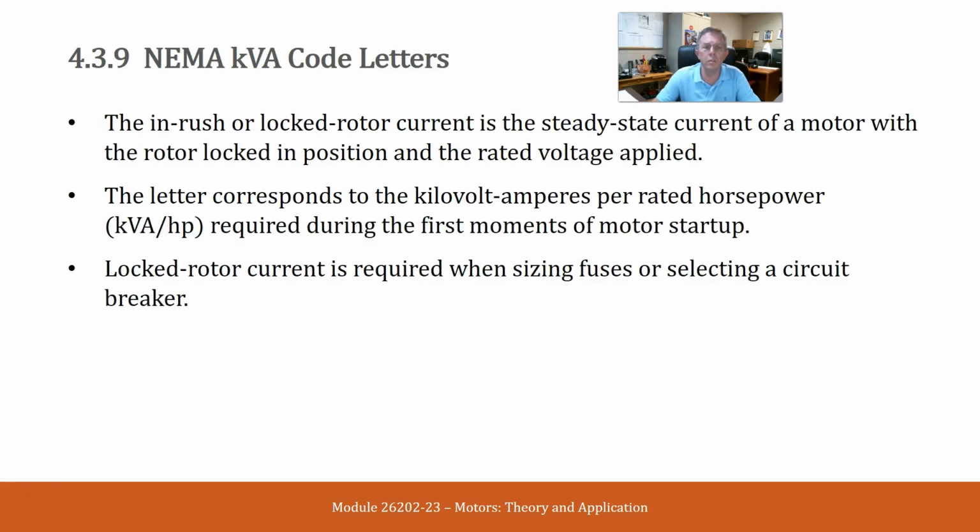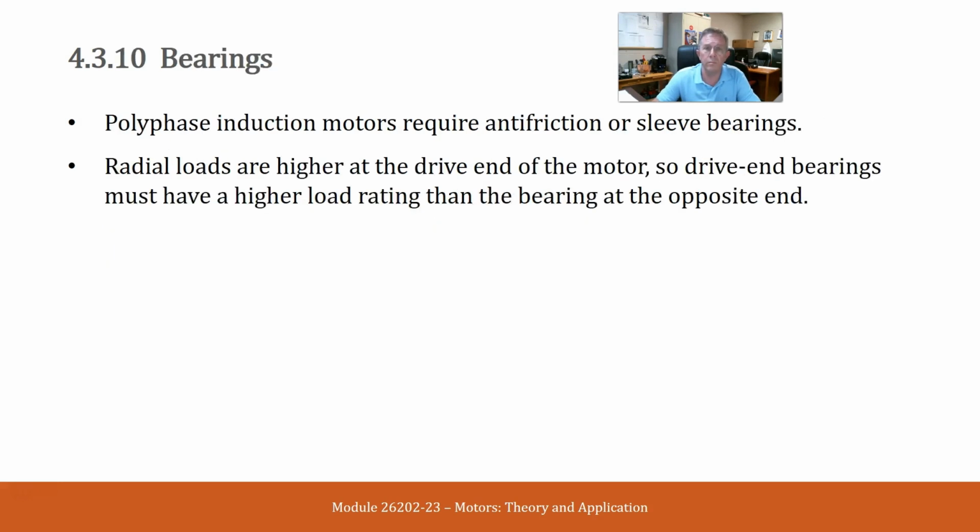NEMA kVA code letters. The inrush or locked rotor current is the steady state current of a motor with the rotor locked in position and rated voltage applied. The letter corresponds to the kilovolt amperes per rated horsepower required during the first moments of motor startup. Locked rotor current is required when sizing fuses or selecting a circuit breaker.